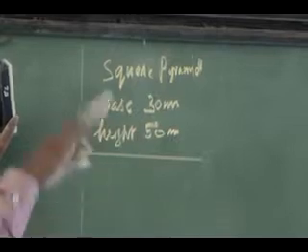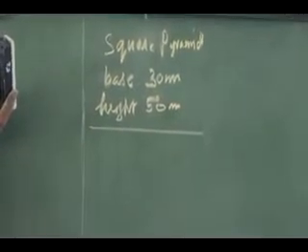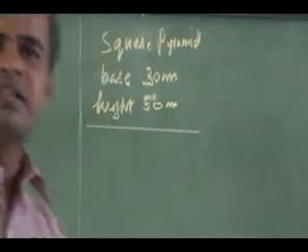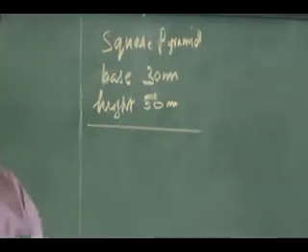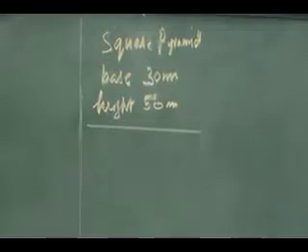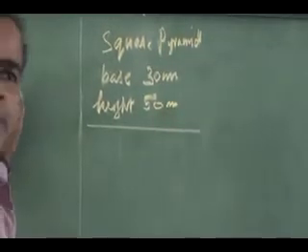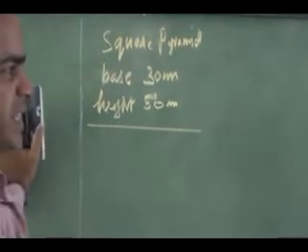In your top view you have to draw a square with the edges touching the picture plane, not at 45 degrees, right? The edge is touching the picture plane in the sense that the edge is parallel and it is touching. So it is similar to the parallel condition, just the behind distance is missing. It's 0. Then the station point